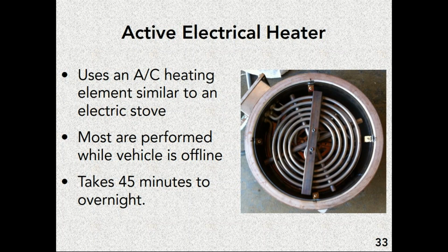Now, it requires electricity, and in my understanding, I don't know of any system that's actually capable of doing this. It's difficult to impossible to produce enough electricity to make one of these work on a vehicle that is actually in transit running on road. The battery systems and the generator systems that on-road engines or off-road engines have just do not produce enough electricity for this to work right. So this type of unit will almost always have to be plugged in. It has to be plugged into shore power so that there's enough electricity to make this thing work.